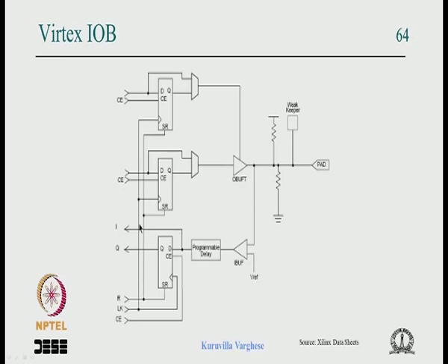Similarly, the input path can be directly taken or it can be synchronized, and all these flip flops have clock enable, and the clock can be chosen from multiple clocks. They have reset and set, and a programmable delay can be added to make the hold time 0, because sometimes the signal is coming from an external source. It could be a synchronized signal, but then the hold time can create a problem, because meeting the hold time is tough. So we can add some delay to make the hold time 0. Once it is synchronized, the hold time will not be much of a worry, okay.